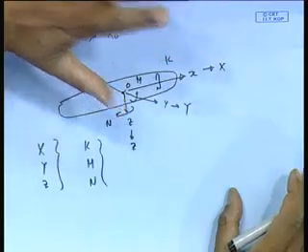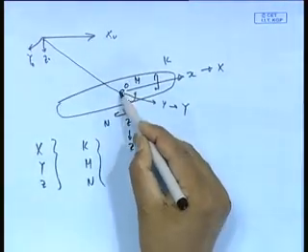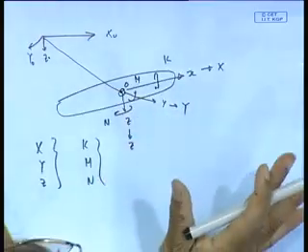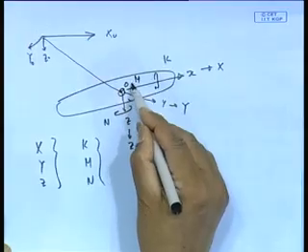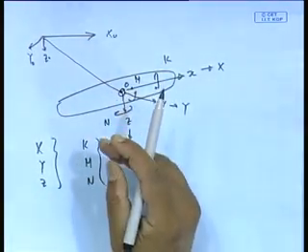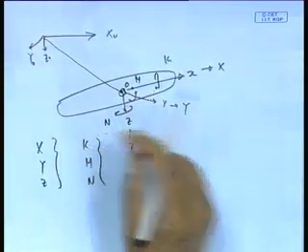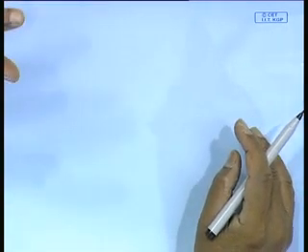if you were to go through the same equation of motion, mass into acceleration is force, you end up getting, and also if you were to take a general point O, which is not necessarily the center of gravity, some point O which has coordinates with respect to the center of gravity x g, y g, z g, means O is located at a point from which the center of gravity is x g, y g, z g, you end up getting the expressions which I want to just show it to you, which is well known, which applies to any three-dimensional body like a spacecraft, missile, torpedoes, submarines, aircraft, anything.